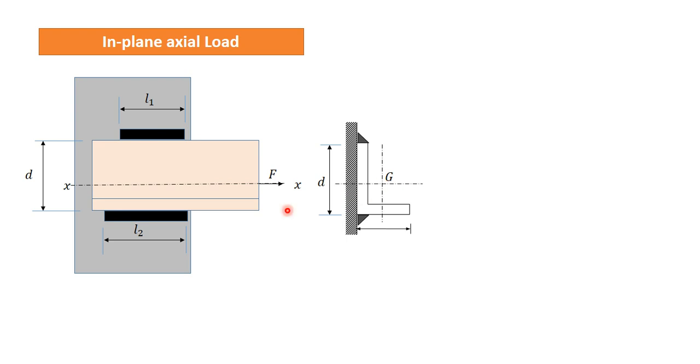To analyze this type of weld, we can find out, for this load, how much total length is required if we know the thickness, or the maximum weld leg that we can use in this case. That total weld length we can apply on one side, or on the other side, or we can distribute it equally, or like this, L1 here and L2 here. How to find these lengths, and in what proportion we should distribute the total length, is the important part of this type of analysis.